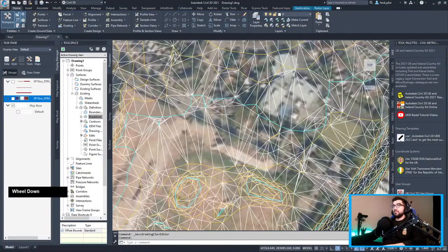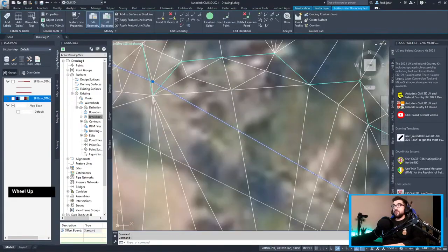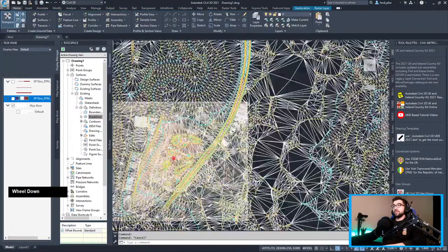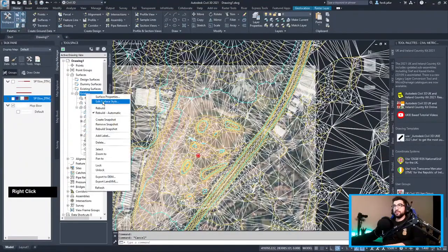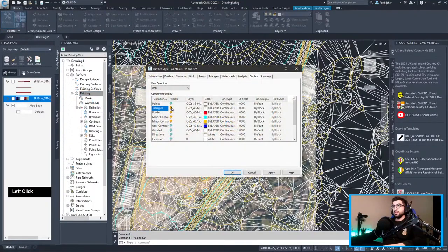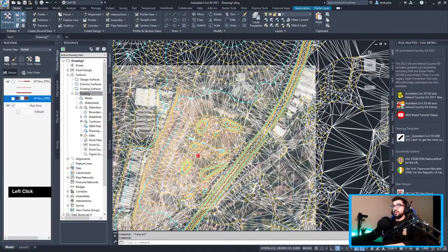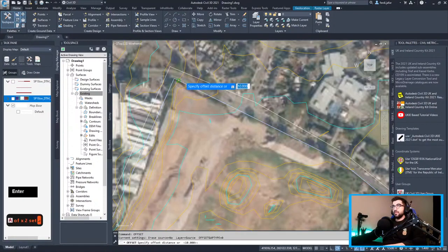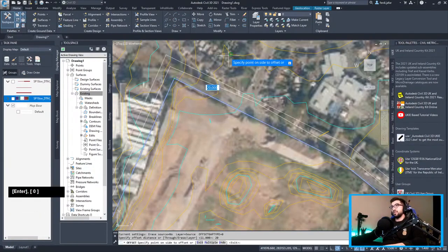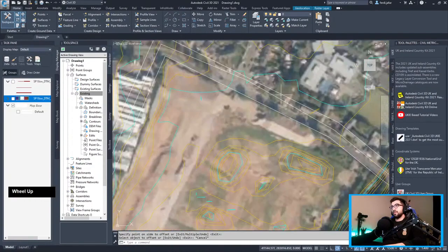And then what I'm gonna do is I'm gonna offset this one. Actually, I'm not gonna offset it. I'm gonna redraw my boundary, so I'm gonna freeze the triangles for now. Surface style, freeze the triangles, and since I have my original boundary there, I'm gonna offset it by 11 meters, let's say. Actually, maybe 20, just so you can see what's gonna happen.